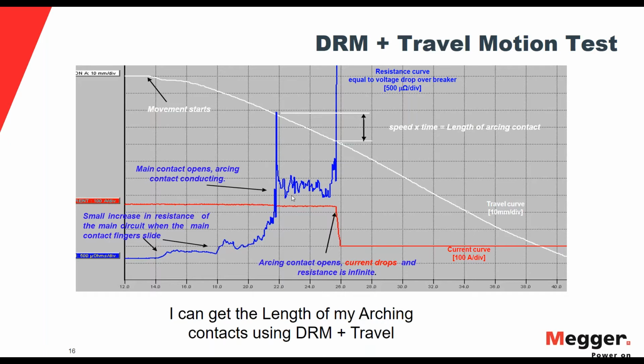So depending on your arcing contact system, when it starts to wear out, especially after huge fault current, you will go to a certain limit, usually specified by your manufacturer. Once you go to that limit, it will not be applicable or even safe for you to operate your circuit breaker, especially in faulty conditions.